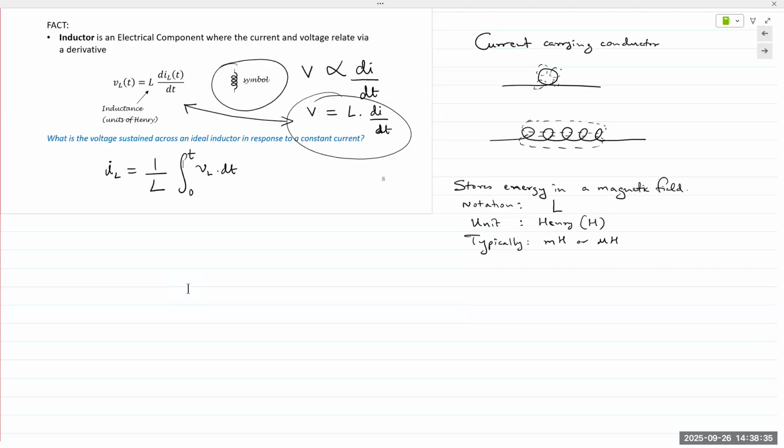The point here is that just because we take a wire and wind it up in a spiral loop, it's not going to change its resistance. The resistance is 0, it will stay 0. However, what happens is, let's say you have current flowing through the inductor. That current is flowing from my right, but your left, to right.